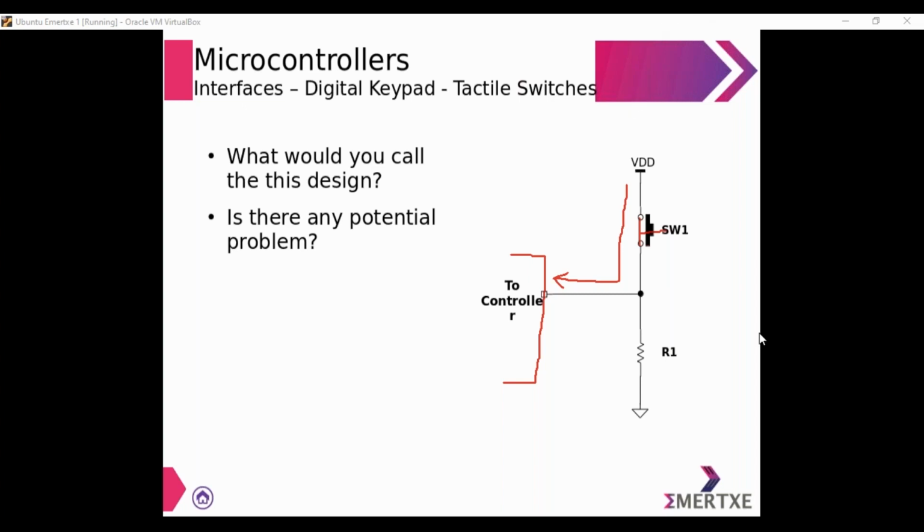It is possible. The complete current without any load is being given to the microcontroller's pin. So more than the required current is flowing to the microcontroller, and due to this, damage can be caused to the pin of the microcontroller. To avoid this, I should add a load, a resistor like this, in such a way that it consumes some power before the current is put to the microcontroller.